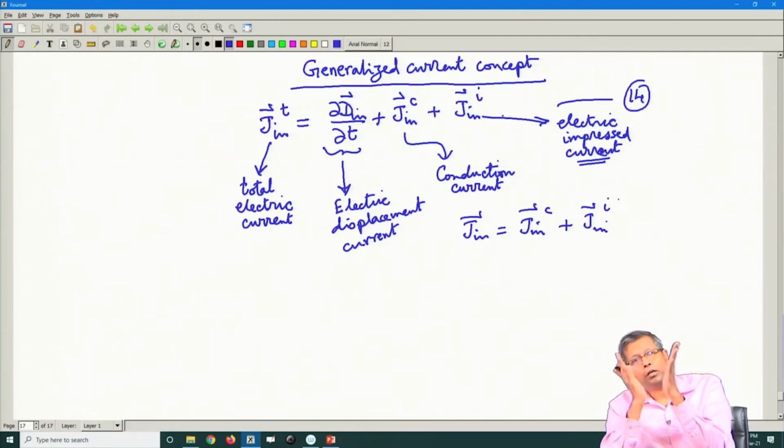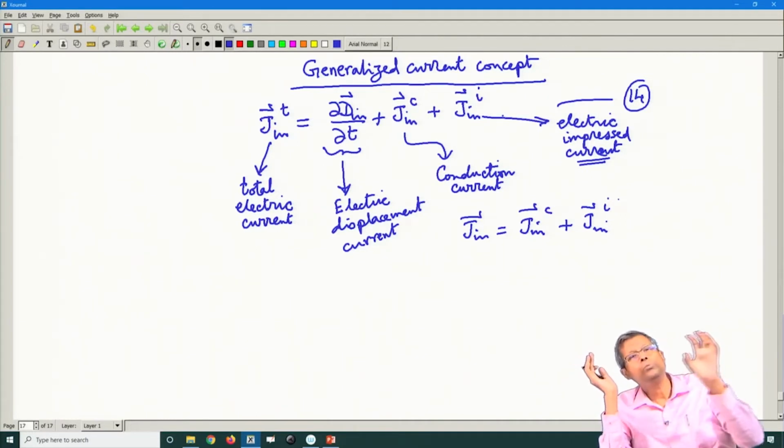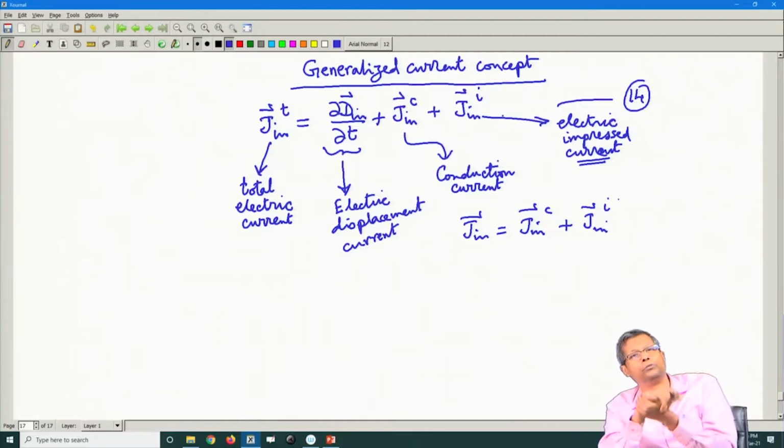The real part of the power consists of the power which is lost as ohmic loss in the conductor and the power that is radiated. Both of these contribute to the real part of the power and to the matching problem, but the part of the power which is radiated is the desired power for the antenna.